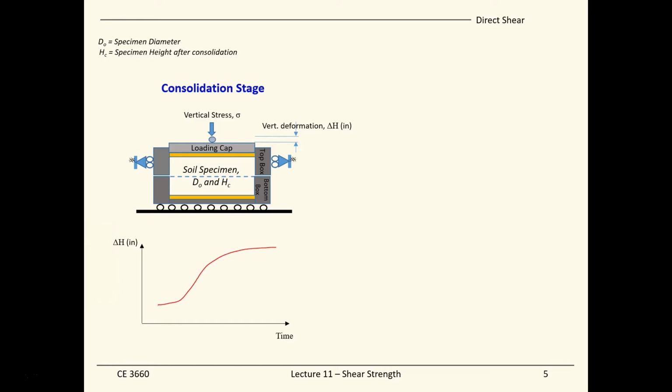It typically depends on the soil you're working on. If you work on sand samples, the consolidation stage will only last for minutes, because for sand it only takes seconds to minutes for the excess pore pressure to expel out. Remember, two lectures ago we talked about clay primary consolidation. Consolidation is about squeezing the water out of the soil sample. So when we have clay samples here, the consolidation stage can take days or weeks to finish.